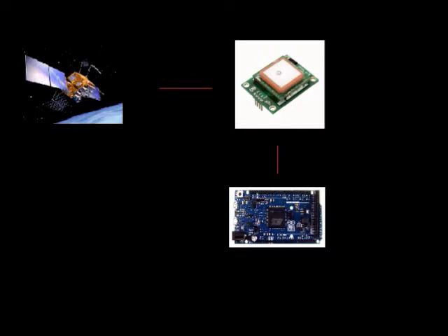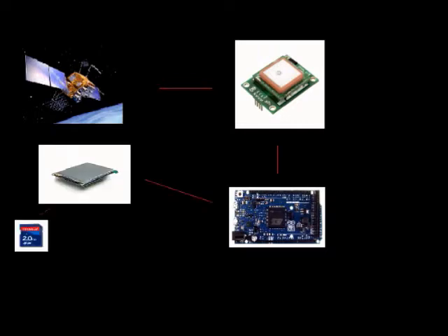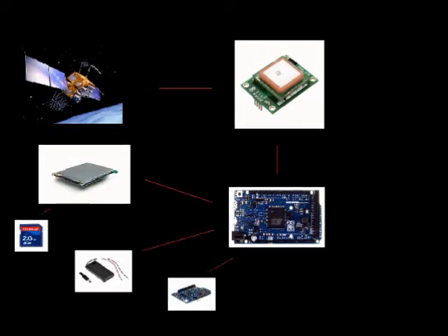Our initial design comprised a GPS unit, a display and SD card shield connected to the Arduino Due, with a battery pack and a Wi-Fi shield. If time permits, we'll transmit to a web server.